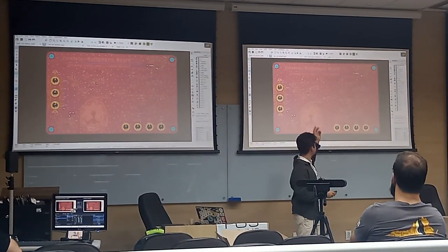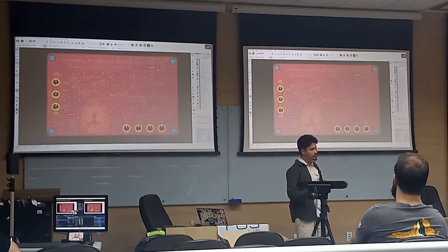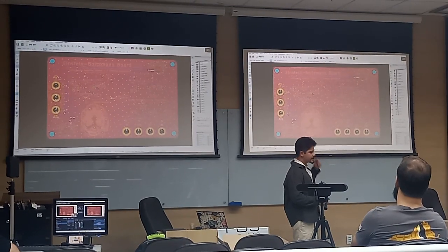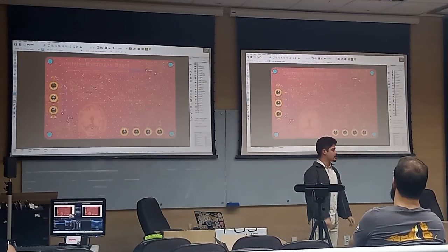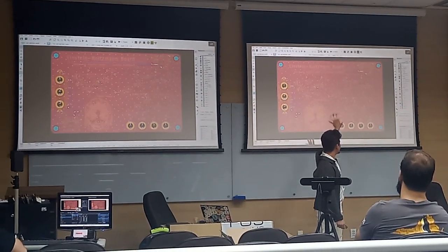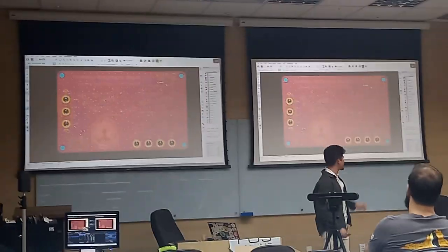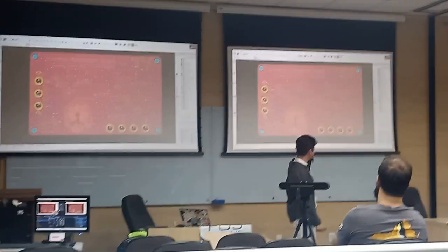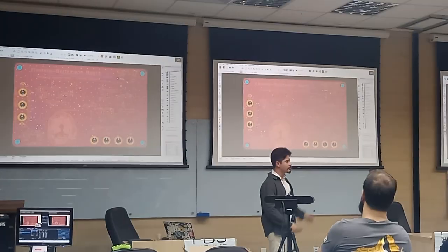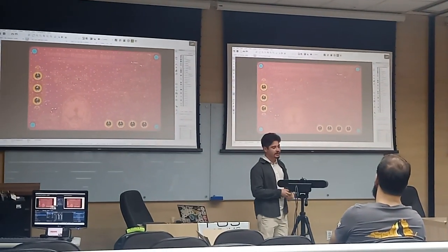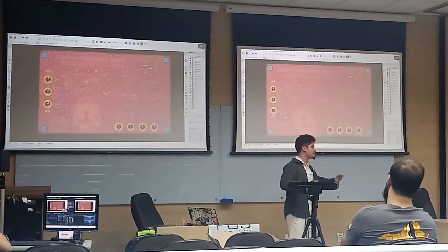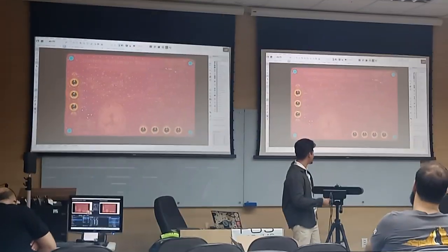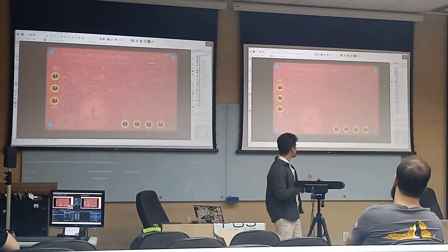Actually, this is the via stitching made with the tool. Very, very fast, very powerful, and they generate vias that are separate from the design. So if you have vias on your board, they will not interfere, and if you don't like this pattern, you can just erase the generated vias and put them again. Very powerful tool. And this was one of the features that Altium has. People say, oh, Altium is much better. But yeah, KiCad also has this feature. Very, very important. And this is the final board actually.